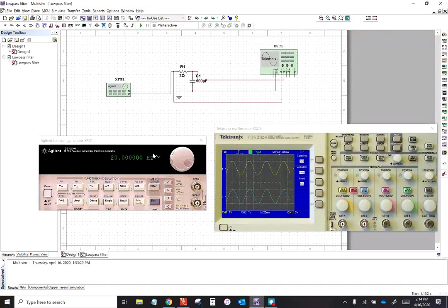Now let's see what happens as you increase the frequency of the input signal. So let's turn on the simulation, and now we'll start increasing the frequency of operation. Notice the output frequency tracks the input frequency. And notice you don't really see much of a difference here. You do notice some change in the phase a little bit, but as you start increasing the frequency of the input, eventually what we notice is that the output amplitude is changing.